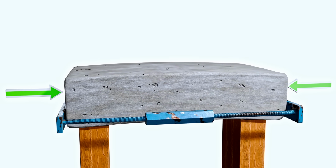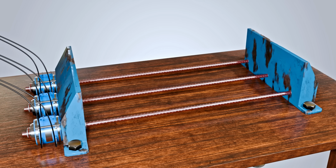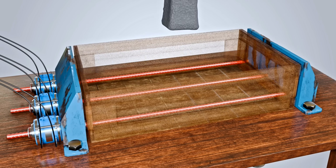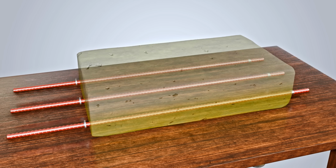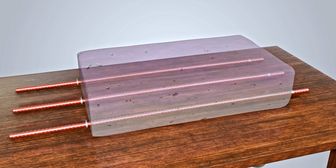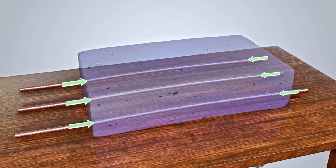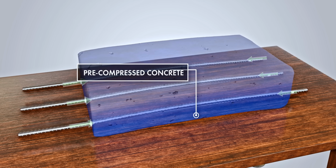But no, we don't compress concrete manually like this. Here's the practical approach. First, stretch the reinforcement bars before pouring the concrete. Then, pour the concrete and let it harden. Once hardened, remove the supports holding the bars in tension. The bars will try to return to their original length, but because they're bonded to the concrete, they can't. This creates compressive stress in the concrete. We have just made the pre-compressed concrete. This new block will have greater strength against tensile forces.